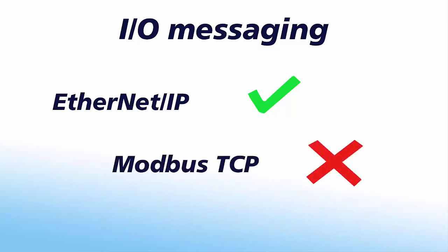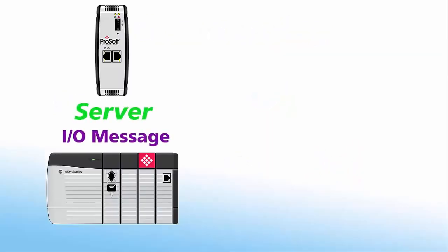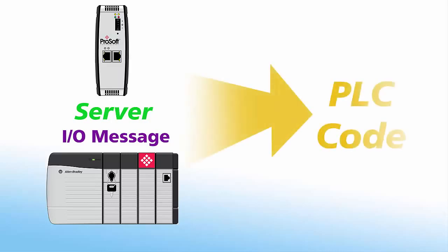Finally, if you want to configure our in-chassis or gateway module as a server or utilize I/O messaging, you will have to make edits to the PLC code. If you don't have access or don't want the hassle, it will have to be configured as a client on the network.